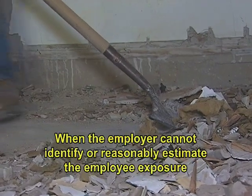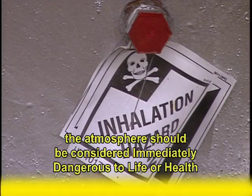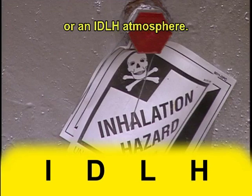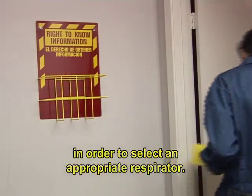When the employer cannot identify or reasonably estimate the employee exposure, the atmosphere should be considered immediately dangerous to life or health, or an IDLH atmosphere. Specific characteristics of the airborne hazard must be established in order to select an appropriate respirator.